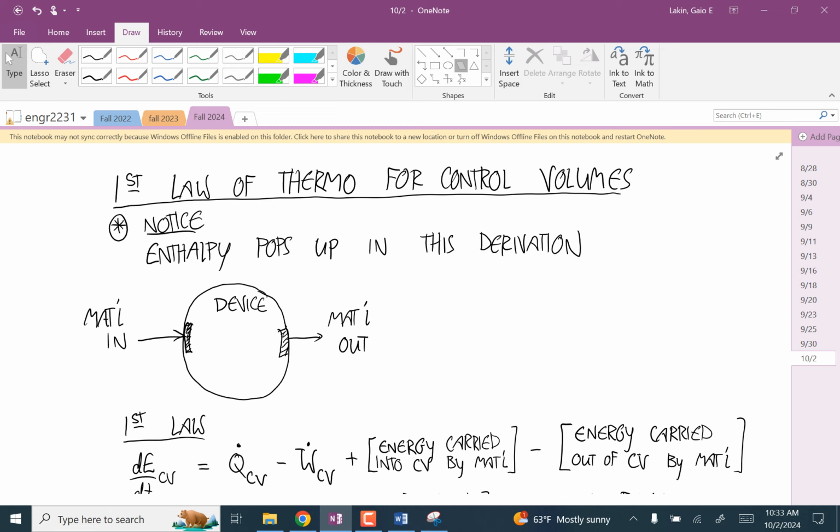But does it have to be? I mean, could there be like a low pressure pulling the fluid out? When you're thinking of absolute pressure, pressure never pulls. When you think of stuff in terms of gauge pressures, you can get negative pressures and suction and stuff. But when you're thinking of absolute pressures, all pressure does is push. It's just a matter of which side is pushing harder. And so the pressure out here is pushing back that way. There's nothing it can do. Even if it's close to zero pressure, it's still pushing a little bit back that way.